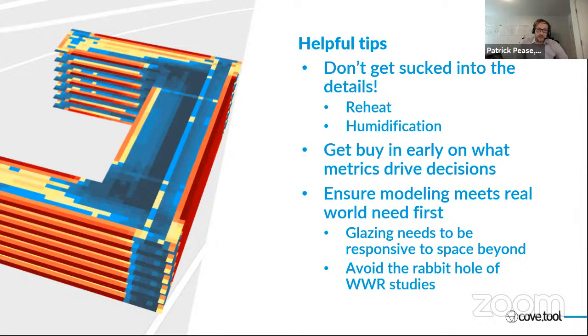And really, if I just looked at percentages on each wall, I'm just confusing things, and I can go down a rabbit hole. The actual answer to the window-to-wall ratio study, that no one wants to hear, is that no windows is the most energy efficient. So avoiding that whole aspect can be helpful, and letting glazing be what it is, designed for the people beyond, can really help.